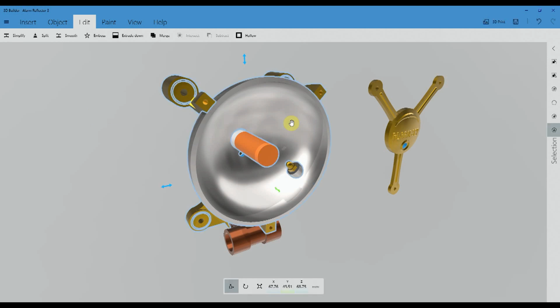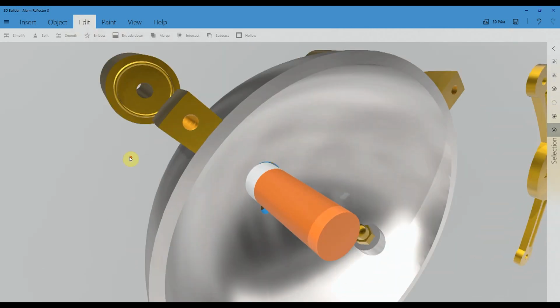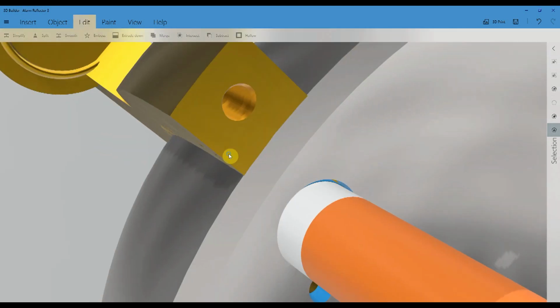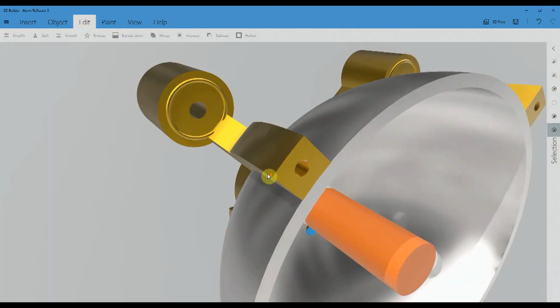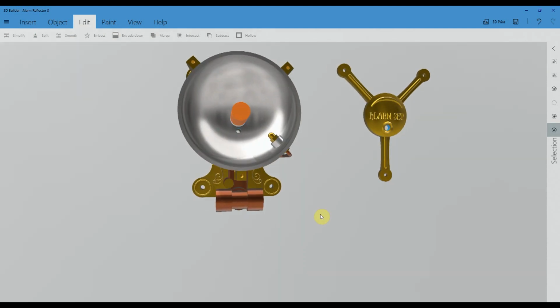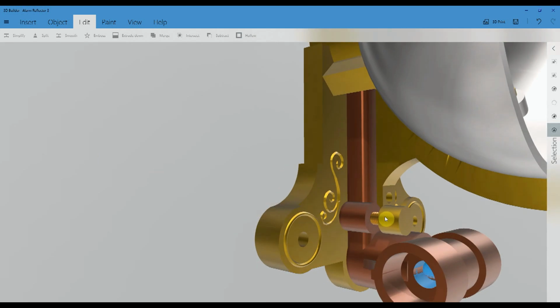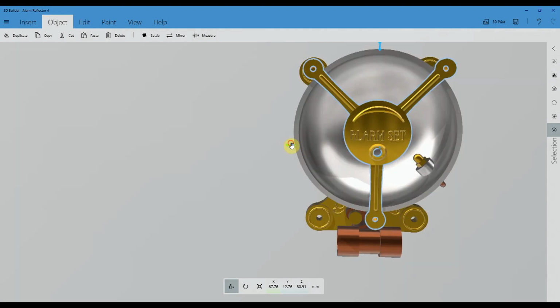With complicated things like this, it sometimes says please wait, because imagine having to subtract a helix, 3 lots of helixes. Oh, it's just amazing. I will zoom in to prove that there is actually a thread cut in there. So that's M3. Because it cuts slightly, it prints slightly larger, I've made the hole 3.2mm diameter. Otherwise it's a little bit tight. I also want an M4 hole there because I've got a brass machined tightening screw thing, so I'll add an M4 hole there.